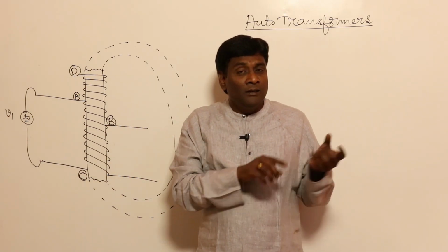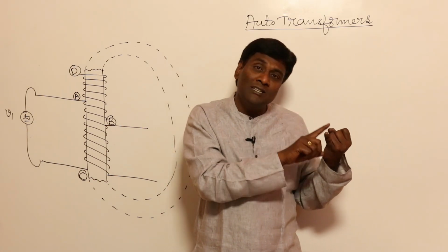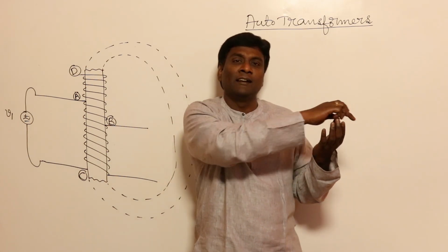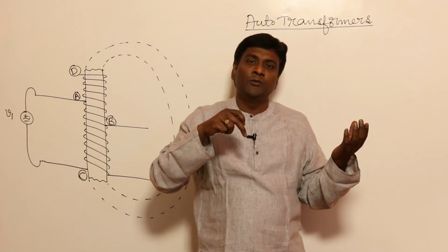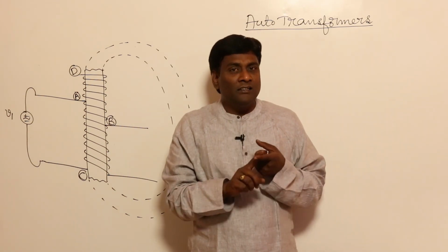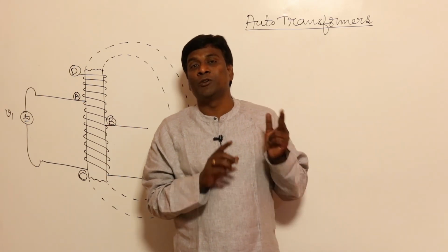The machines lab rheostat resistivity is high, so resistance is high. If you insert iron inside and close the iron path, inductance effects also will be high. Under that condition, both resistance and reactance effects have to be modeled for the machines lab rheostat.